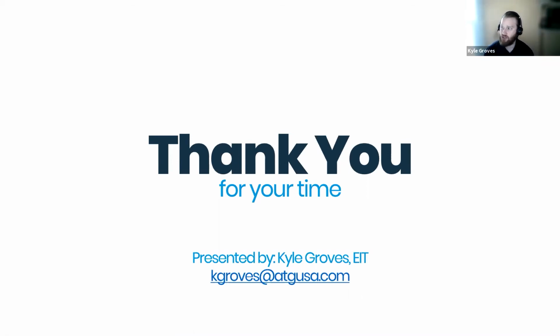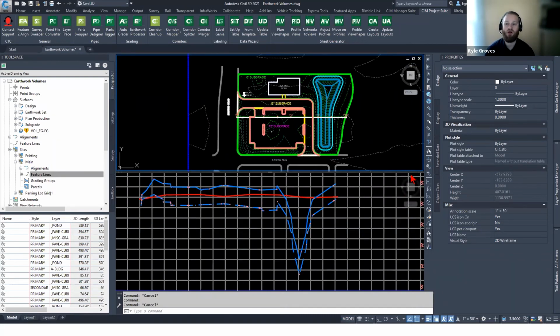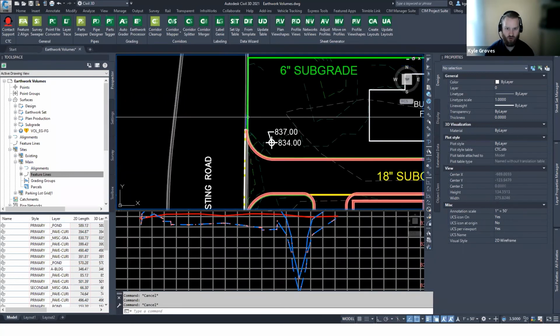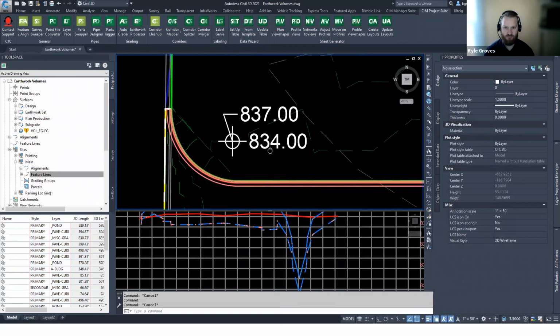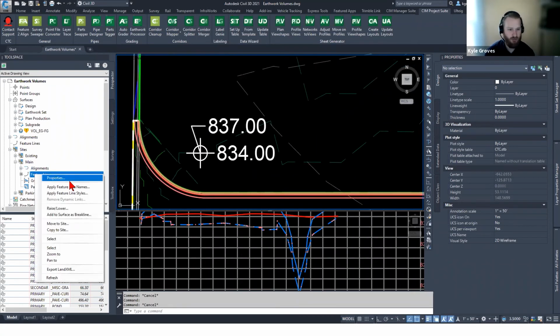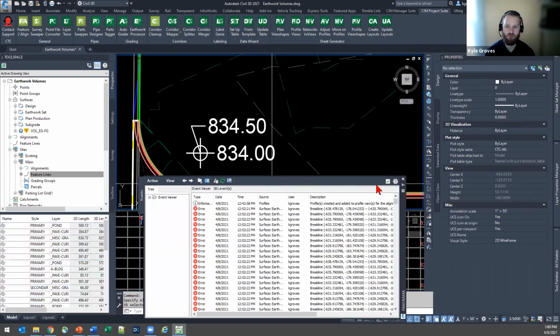Anonymous, the subgrade near zero surface. Can we go over that again? Yeah, for sure. So I'm going to hop back here into Civil 3D. And what we're doing with this is we're just doing algebra, and we're tricking the software into giving us the information that we're looking for. So I have a finished grade surface. That finished grade at this point in time is at, oh, hold on, let me drop my feature lines back. See, I went up 2.5.